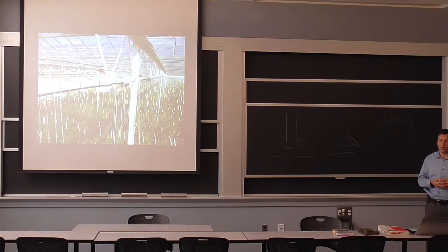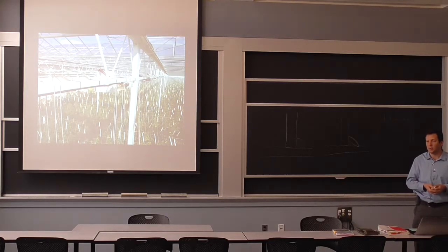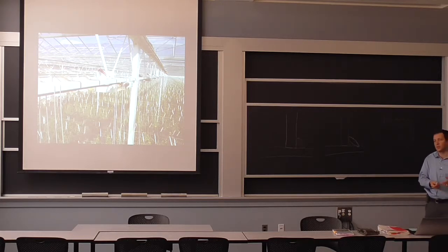We think of roof loads in pounds per square foot, and there are very specific requirements depending on where you are in the U.S. for how much you're supposed to take for that snow load. Typical would be 30, 40 pounds per square foot, so it's a fair amount. If you're looking at the floor of a reception room, they say 100 pounds per square foot, so you can't stack that many people in one area. So that's a little bit how these are built in terms of figuring out your demand.